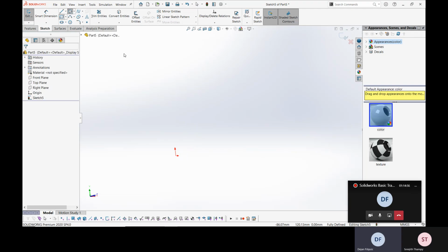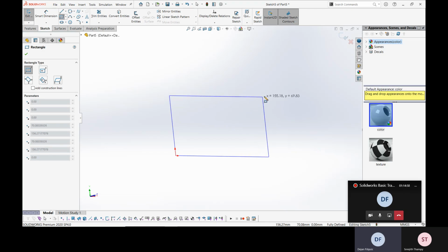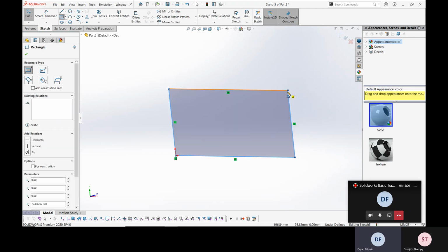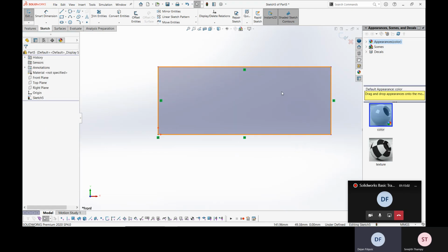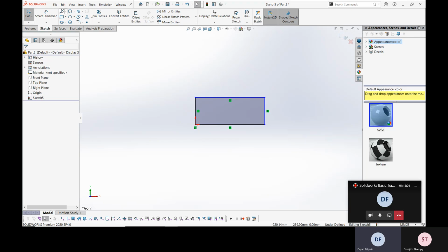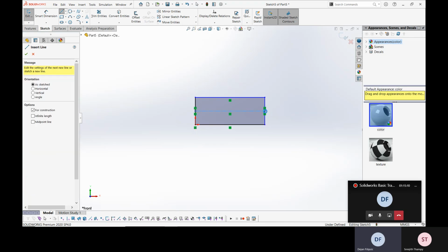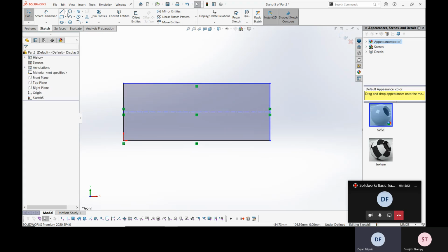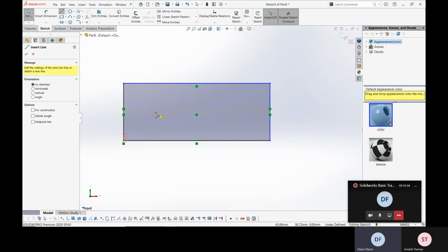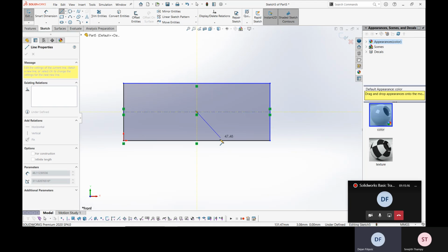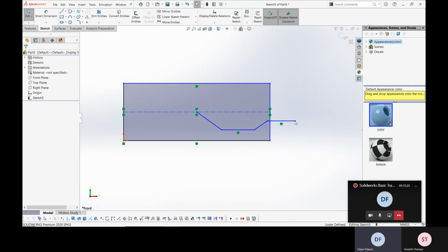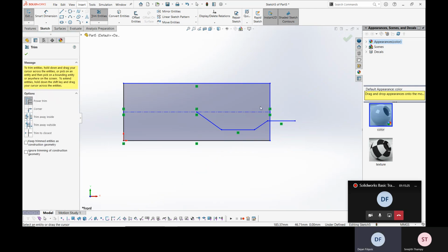If you want to create a certain feature in a certain position on an object, you can use the outline as a reference. You can dimension to it, or you can make a line that acts like a reference line. So you can just make a line and then convert it to a reference line, just to show how that works.